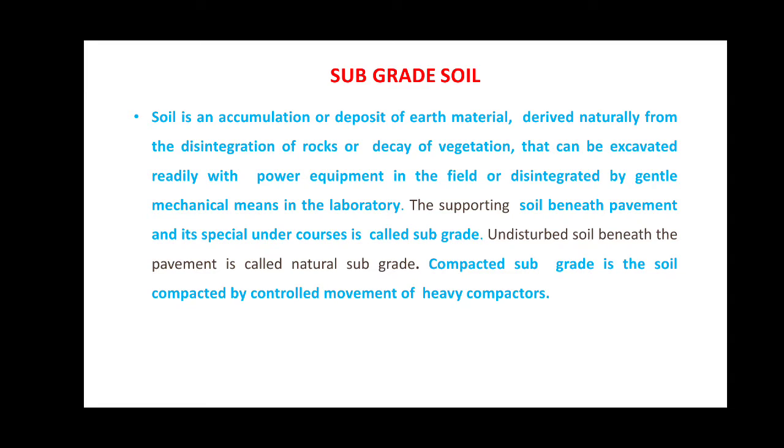The stress-strain behavior of the soil under static and repeated loads also has significance on the pavement performance to a great extent, and it depends on the subgrade soil properties and the drainage capability of the soil.